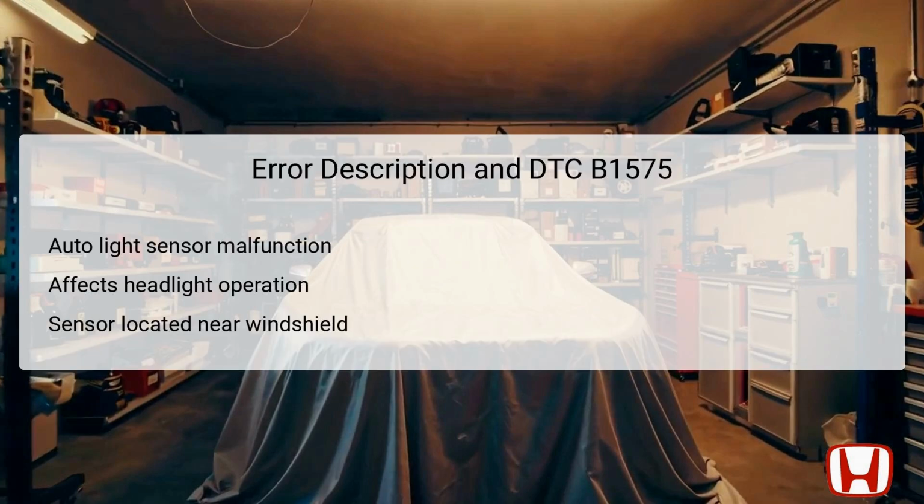DTC B1575 signifies a disruption in the auto light sensor circuit. The automatic lighting sensor, positioned near the windshield of the Honda Odyssey, detects varying light conditions and regulates the headlights accordingly. When functioning correctly, this sensor enhances the vehicle's safety by adjusting the headlights in response to external light levels, such as switching on at dusk or in tunnels.